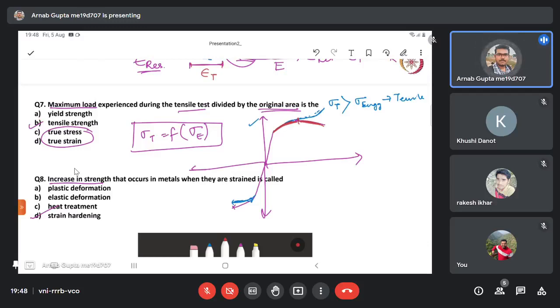So with strain, the material becomes softer because local voids are there. And due to these local voids, if we take this cross-section here, the actual area which is resisting the deformation has decreased suddenly by a large amount, and that's why the material starts necking and then it fails.